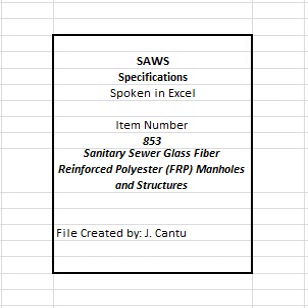F. Acceptance. Any manhole which fails the initial test must be repaired per manufacturer's recommendations. 1. The manhole shall be retested as described above until a successful test is attained. 2. After a successful test, the temporary plugs will be removed. 3. To ensure that the plugs have been removed, contractor shall only remove the plugs in the presence of the inspector. G. Repairs to existing manhole.